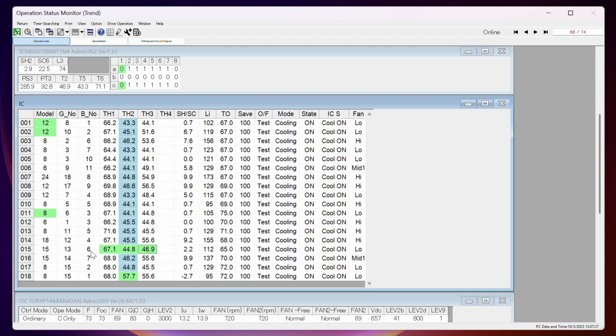So what this would mean is that after I finish my port verification, because you want to go through and do all of these, you would go ahead and take this and change this on fan coil address 15. You're going to change dial 6 to dial 1 based on what port it's actually on. And that is going to conclude